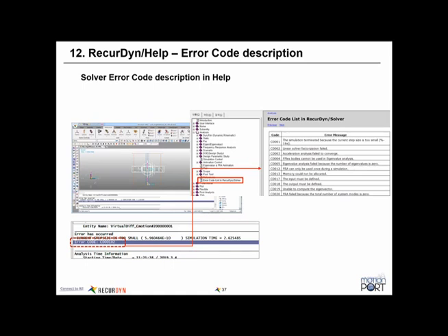So in ProcessNet, we could monitor penetration and then automatically go back and rerun with a higher stiffness if needed, and continue to do that until the penetration was down to a low enough value to be acceptable. So with ProcessNet, there are some things we can do to address certain issues, and with ProcessNet iterating, it's a lot faster than manual iteration.